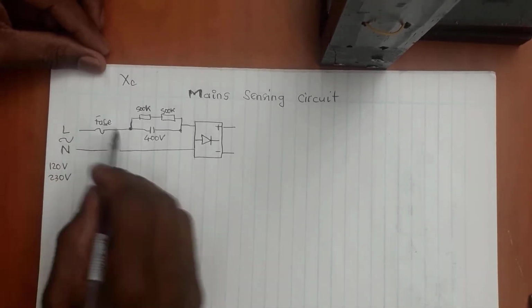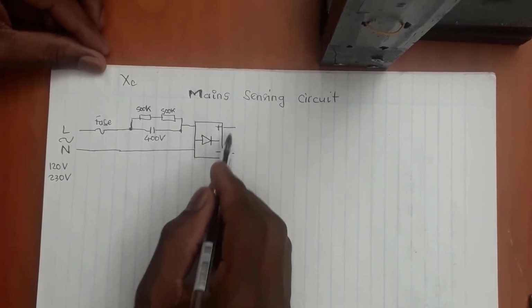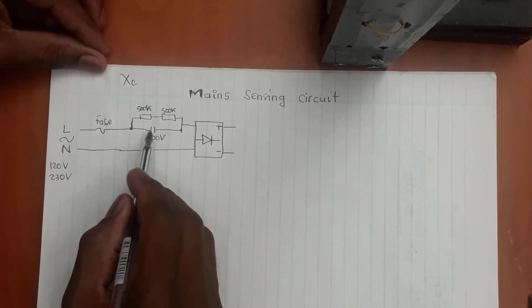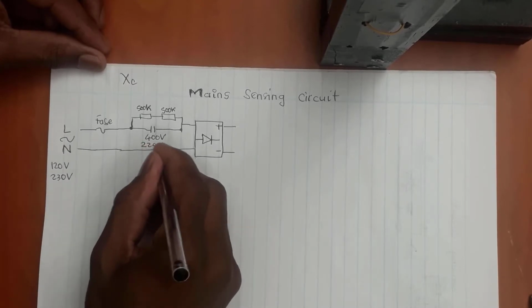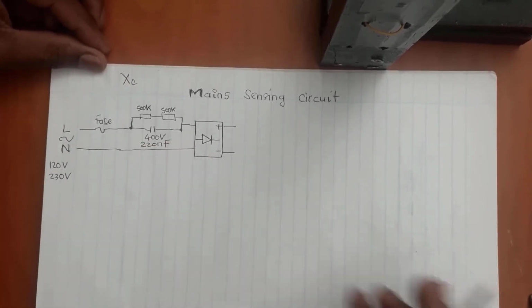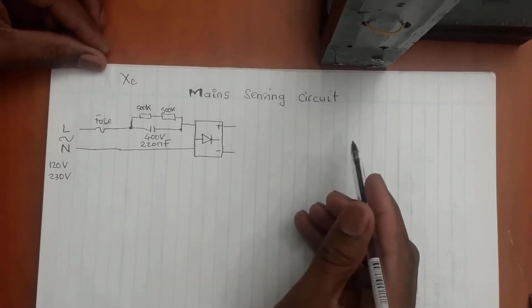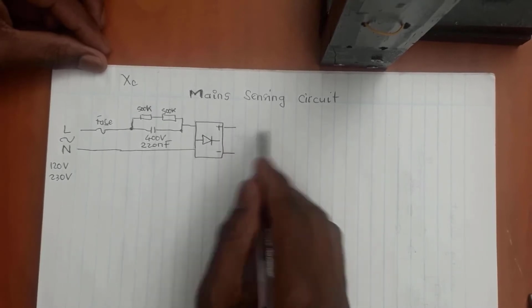We fully rectify our AC, and the current going through this bridge here is limited by the capacitive reactance of this big capacitor here. Okay, now let's say we put a 220 nanofarad capacitor here. We know that we're going to be limited by the current here. We're going to calculate that later. Okay, so what's happening here now, we can then configure from the output here.